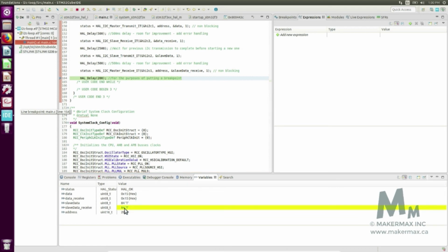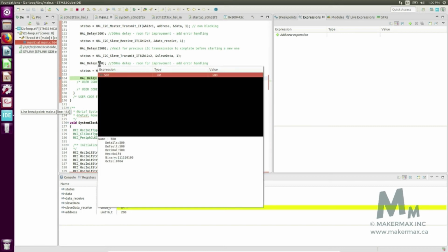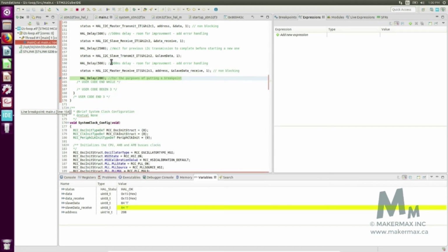So the reason why sometimes this is not sent, and why this is sent, is because 500 milliseconds might be at the very threshold of how long the transmission is going to wait before a receive acknowledge is received. So we probably should reduce this value. But again, for the initial implementation, it's fine to base it on some random trial and error values for the millisecond values for actually having a transmission.